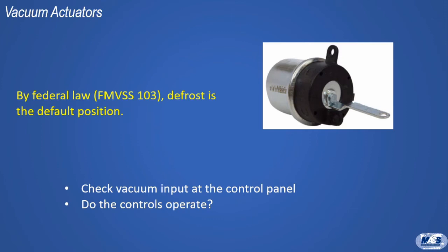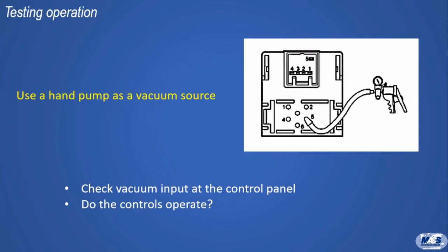No, nothing wrong there. The technician did notice a slight air noise on acceleration. So, where can the leak be? He removed the control panel and checked for source vacuum at the function control switch with the engine running. It was good, so he checked the operation of the function control switch with a manual vacuum pump, and no leaks showed up. Then he checked the mode vacuum switch assembly, but again, no apparent leaks could be found.